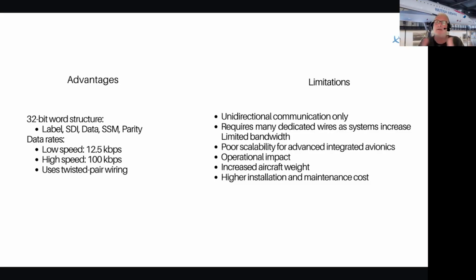It's like Boeing when they made the 787. They decided to make the whole fuselage carbon fiber to save weight. And then they saved so much weight that they had to actually cool the avionics with coolant. It was the lengths they went to cool the avionics, and all these systems added so much weight that it negated the weight they saved when they made the fuselage. Same here. We tried to save weight by becoming efficient.